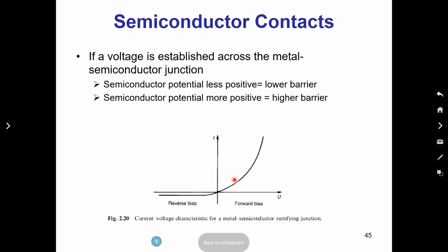So the threshold voltage that you need to apply to get current decreases. Meaning that this IV curve will keep on shifting to the left as you increase the gas concentration. And then the shift in the IV can be calibrated to the gas concentration. Well, this is not desired for electrical conductivity measurement. People use this as a device.